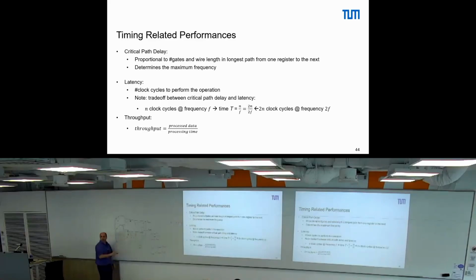So the latency of the overall thing is the same, but every clock cycle, now with 10 nanoseconds, one result drops out. So if we do enough processing steps, then we see effectively the throughput of 10 nanoseconds, one clock cycle, instead of before 11 nanoseconds, also one clock cycle.